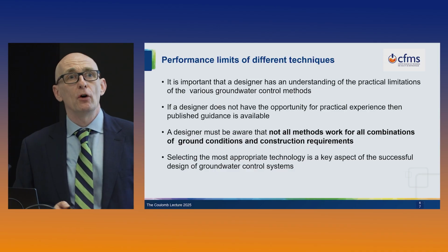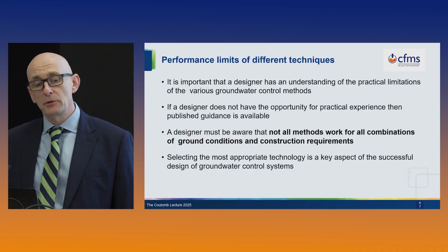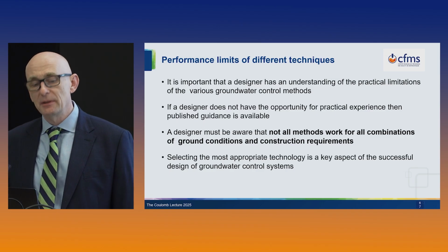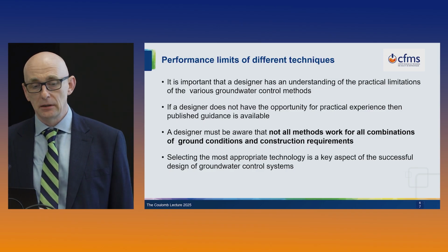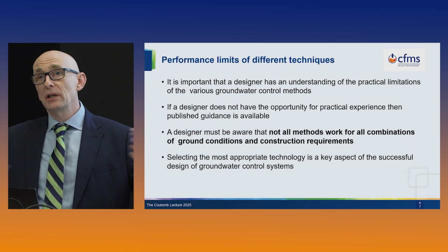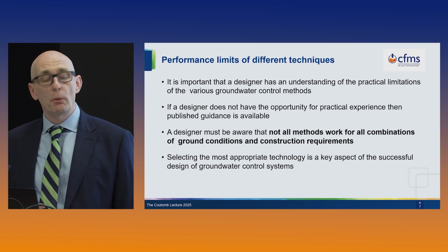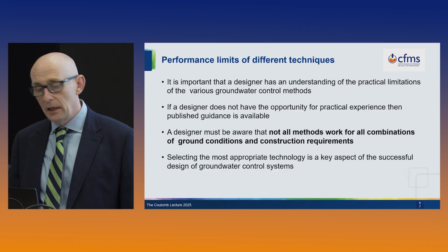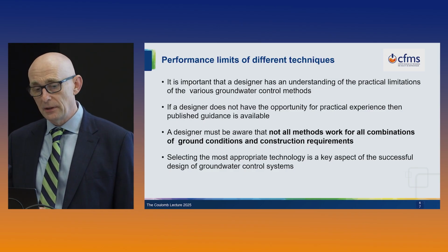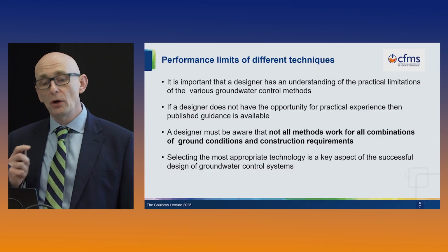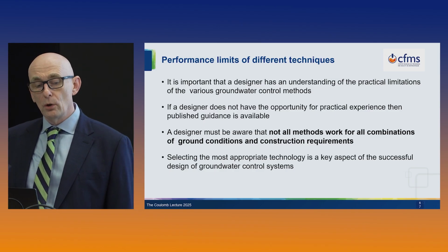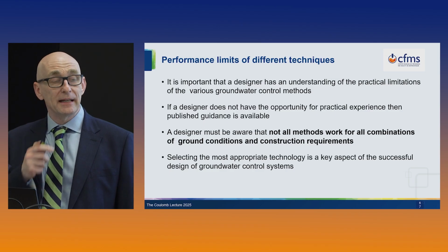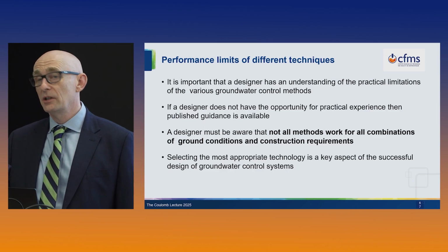I want to talk about the performance limits of the different ground control techniques, because I think it's important that a designer has an understanding of the practical limitations of the various ground control techniques. I understand that depending on your organisation, not every designer has the opportunity for practical experience, but there is published guidance available to give you some indication of the performance limits, because the designer must be aware that not all methods work for all combinations of ground conditions and construction requirements. And selecting the appropriate technology is a key part of a successful design.